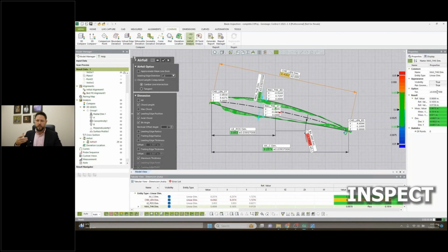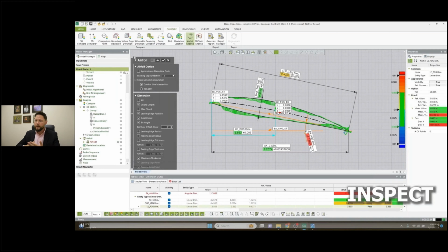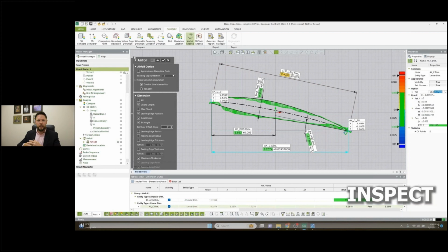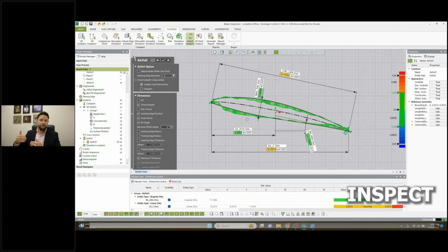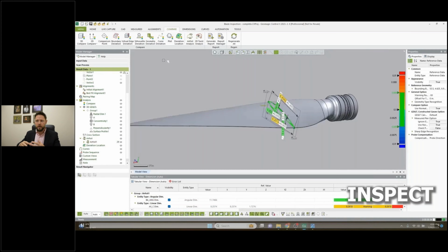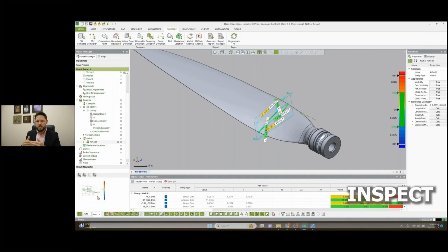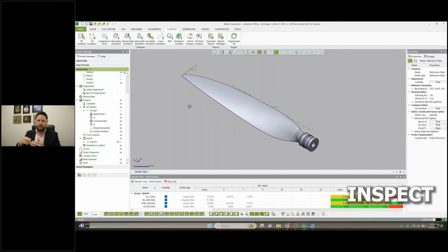All right, we can adjust tolerances here, to replicate exactly what you have on your call out sheet. And then once we're all done with that, we click the checkbox, and that applies to our inspection program. Now, you may have 10, 15 of these, or 5, or however many in your actual inspection protocol. You can set them all up ahead of time. That way it measures all this when you scan your first blade. But that's how quickly you can apply these types of things.